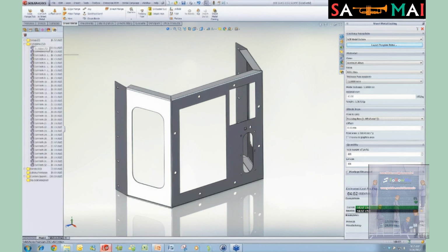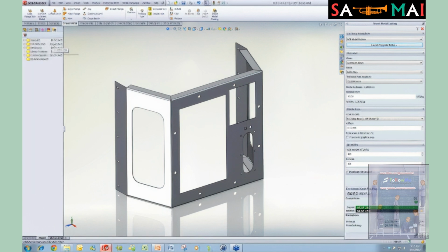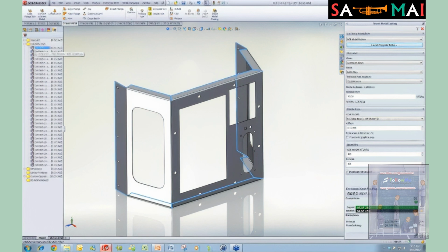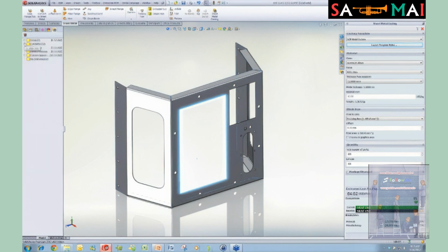The cutting paths, we've got 32 different cutting paths for a total value of $13.27. We can look at each one of these. The very first one, it's kind of the biggest in here, and it's 2,521.69 millimeters, the perimeter around this whole outside. And you can see in the graphic area, it highlights that edge. So at 1 cent per millimeter, it's going to cost us $12.61. So it rounds up a little bit, to be on the safe side. And you can go through each one of these, and you can see, all right, well, that one is this bottom hole down here. You can go through each one and kind of see where the cost is coming from. If that's a big cut area, it's going to cost a little bit more. So I'm going to add all those up.